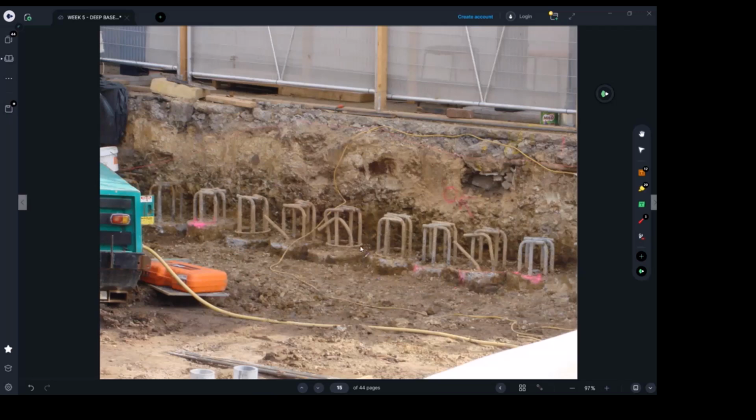All right, same concept, nothing new. You still have a gap. Day one, you're going to do the excavation. The only thing I would mention to you, we use something we call hit and miss. What does that mean? Hit and miss means it's difficult for the builder to excavate this, then that, then this, because the holes are very close to each other, right?